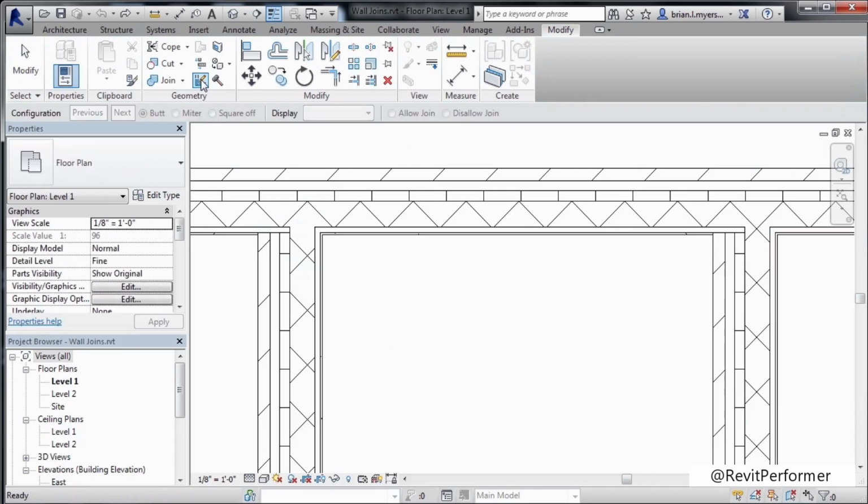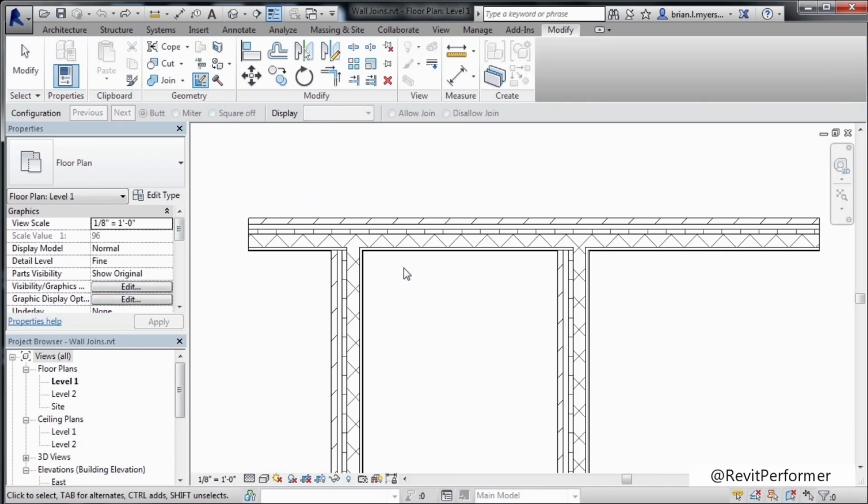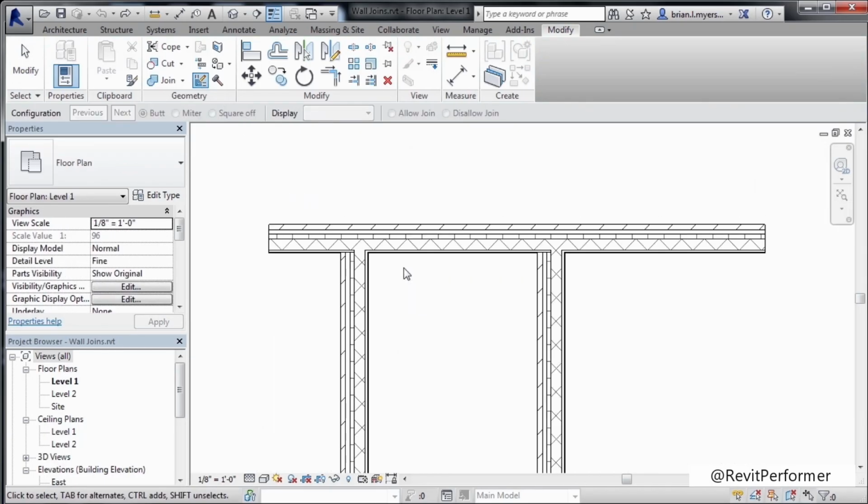After selecting on Wall Joints, you may need to zoom out just a little bit to see this big box that's going to show up. Highlight over the intersection of these two walls, and you'll see this gigantic box pop up. When you click, you'll notice that we have options on the options bar as far as how these walls can join up.